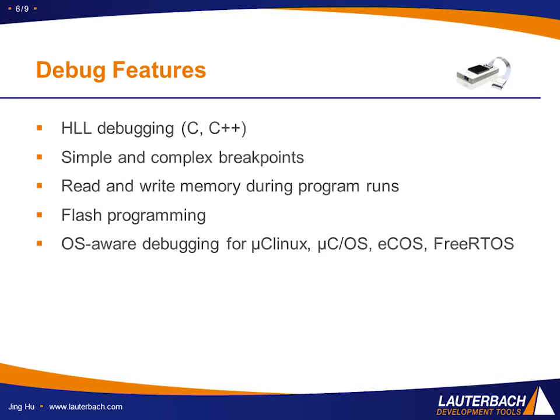As a debugger, Microtrace supports high-level language debugging for C and C++, setting simple and complex breakpoints, reading and writing memory during program runs, flash programming, and operating system-aware debugging for uClinux, uC/OS, embOS, FreeRTOS, and so on. For more than 10 years, we have been supporting multicore debugging, and so does Microtrace.